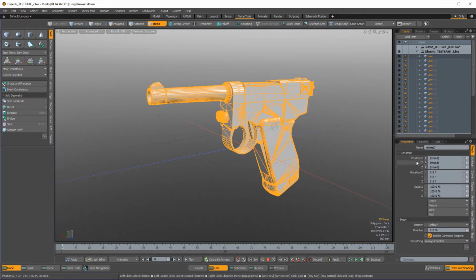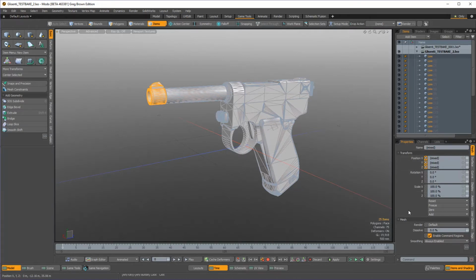And so if I go ahead and pull this on up, I want to select, in this case, positions. And I'm going to go ahead and keyframe X, Y, and Z for every item just to make my life a little bit easier. I actually could just keyframe X if I wanted to, just by selecting that alone. But I can select one item followed by the other, or one channel followed by the ones below it, and it will gang select all of them for me, which is pretty cool. So once I have channels selected, if I'm in item mode, I can hit the S key, and you can see it set a keyframe right here for me, which is super useful.